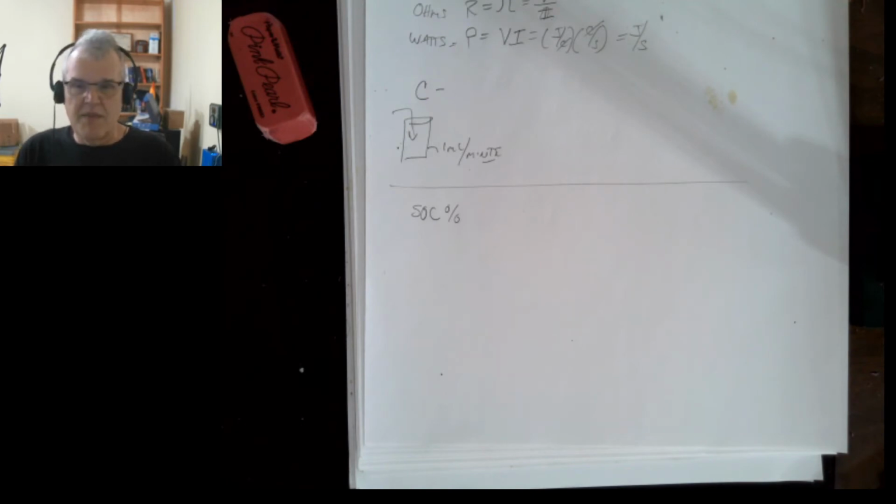Internal resistance, then. What is internal resistance? Well, every battery has chemicals in it that are going to move from point A to point B to be able to create this potential, and so there's some restriction for those movements of those chemicals, and there's other things that happen in the battery that build up a resistance inside there. So every battery has some sort of internal resistance.